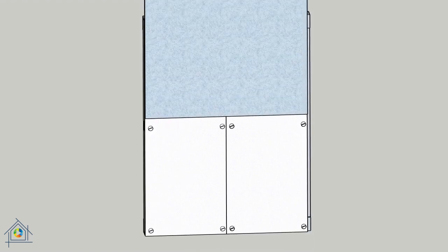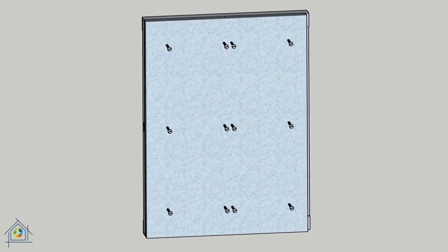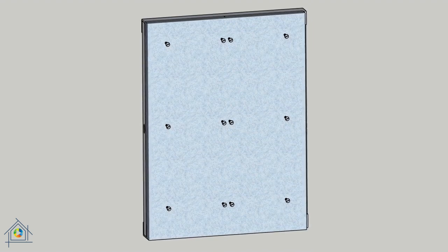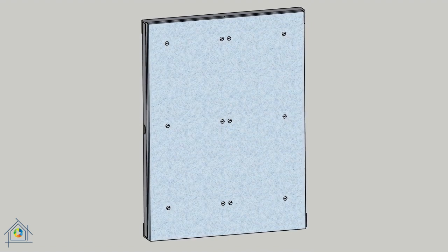On the first layer, moisture-proof prefabricated gypsum boards are installed. These boards are attached to the LSF structure using screws. The screws used are 4 centimeters long and 30 centimeters apart for installation.